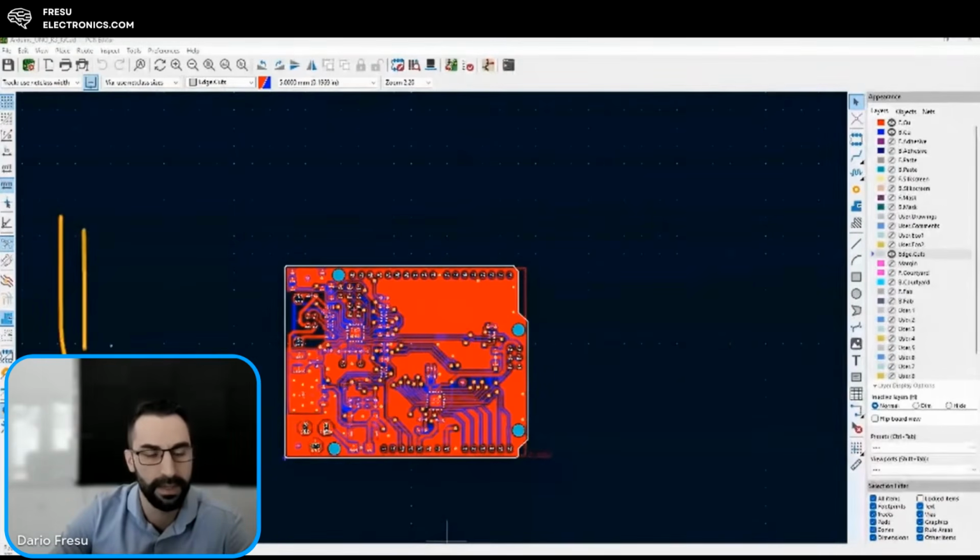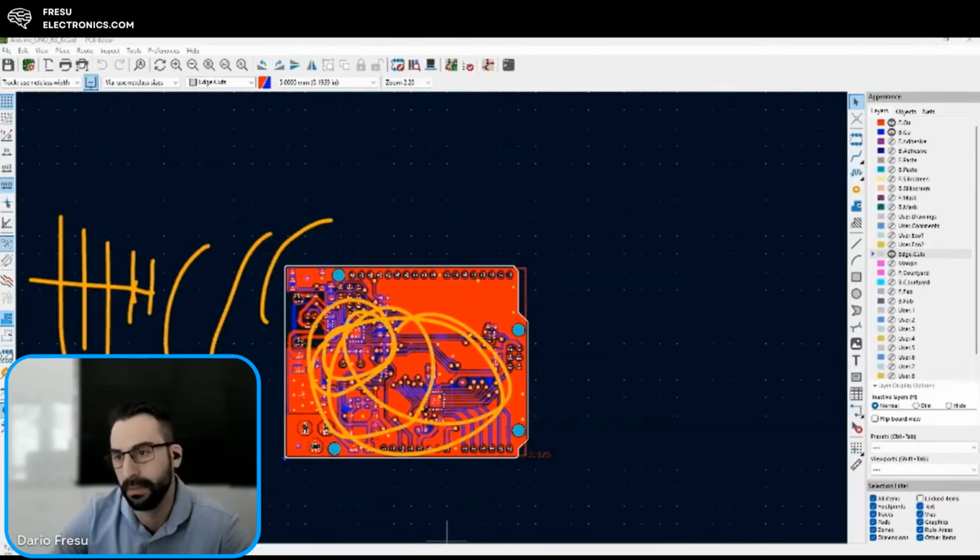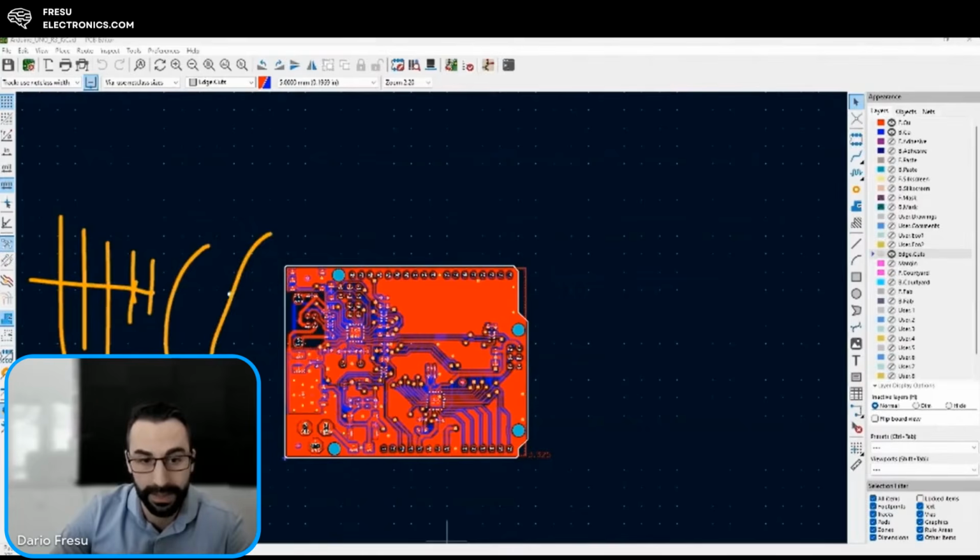And so if I have the antenna here trying to measure the fields, what is going to happen? I'm going to catch these fields in here, and they're all coming from this printed circuit board. So if I can create the structure that clearly contains all this field, what is the antenna going to pick up in here? Barely nothing. So this is how simple electromagnetic compatibility becomes. It's just a test of, did you design the board correctly or not?